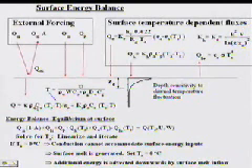And then the coefficients in the front here are the density of snow, the heat capacity of ice, and a thermal conduction parameter. You can group these all together to define a surface conductance, which is this Ks term here.